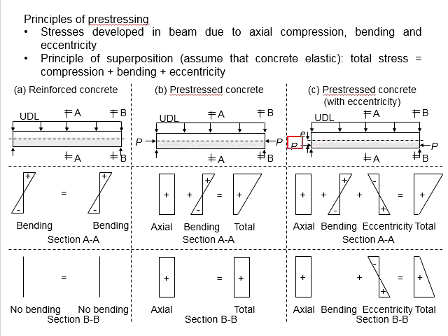Due to the compressive force caused by the pre-stressing load, there will be axial force acting on the member. Due to the external load acting on the beam, there will be bending moment stress acting on the member, tension at the bottom of the beam, and compressions on top of the beam.